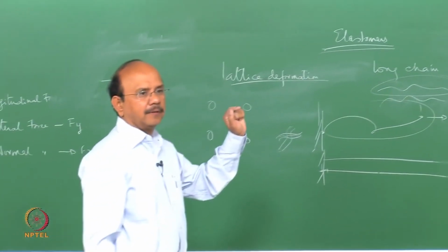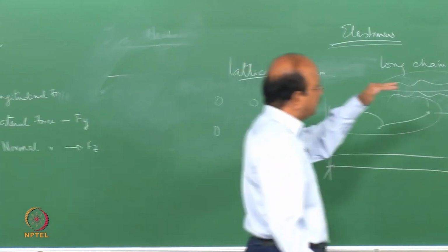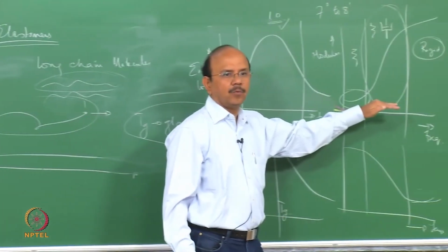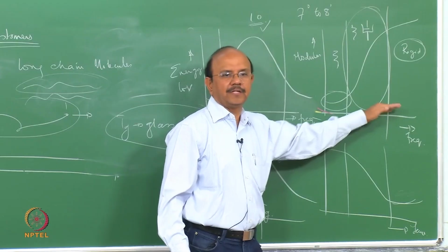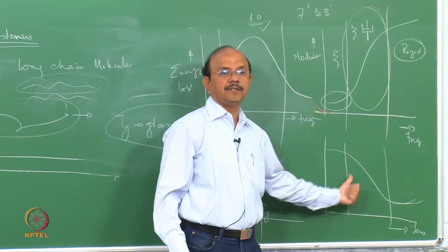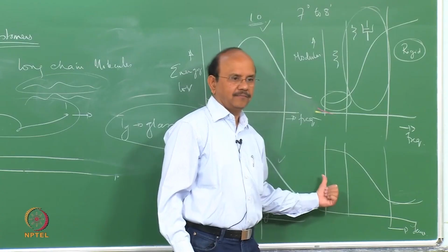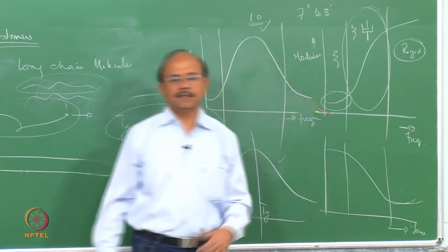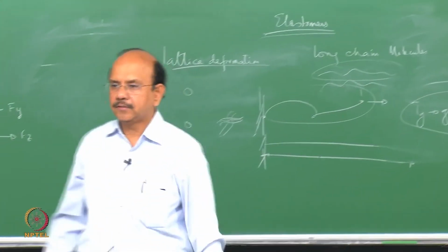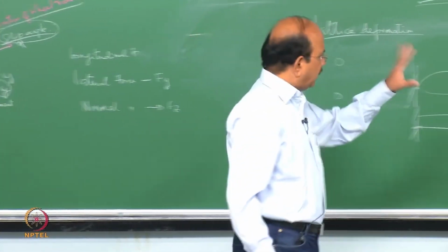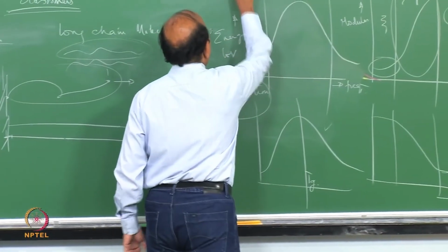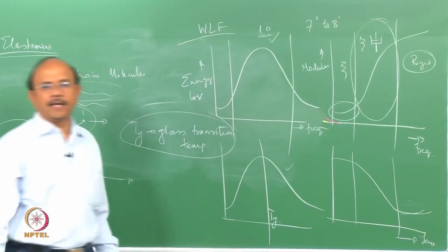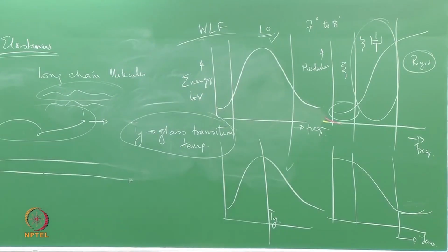When I increase the frequency, would the temperature increase or decrease? Decrease. So you go this side in frequency, you would come the other side in the case of temperature. There are equations for this, given by Williams, Landel and Ferry, the WLF equations. We will not go into the details, but we will understand this more physically.